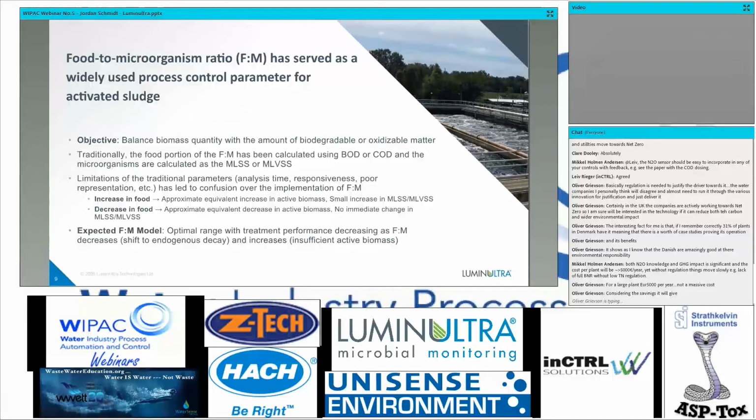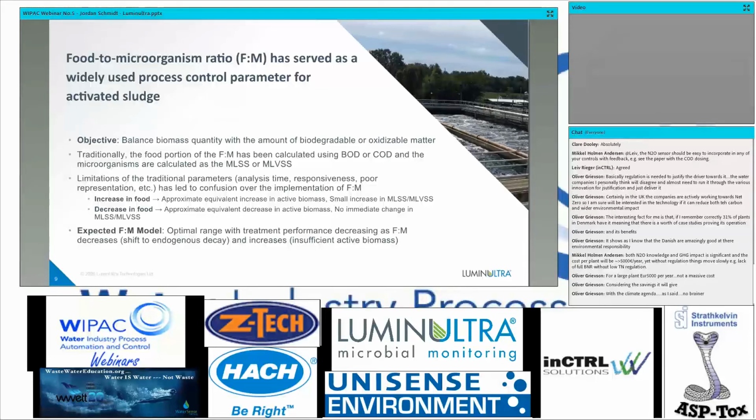The expected F to M model would have an optimal range, with treatment performance decreasing as F to M increases and there's a shift to endogenous decay, but also decreasing as F to M decreases, as there's insufficient active biomass. So it's going to go in a bit of a curve like that.